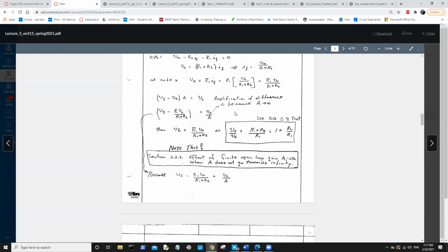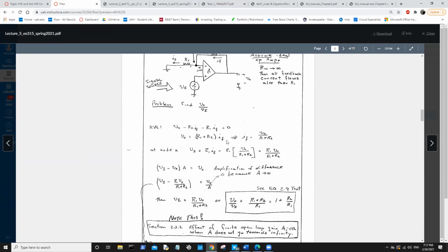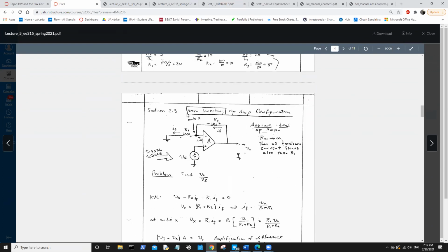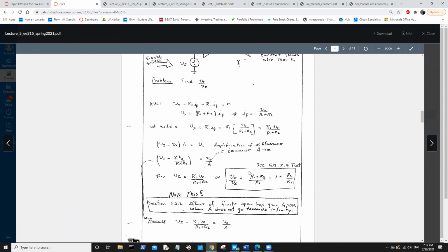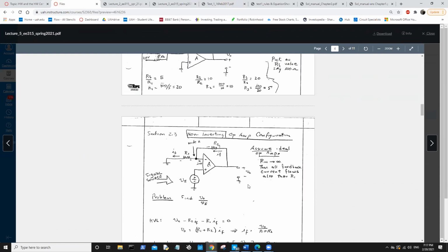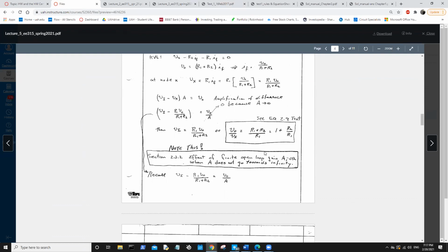And that one probably, if you want to look at the derivation, probably lines up exactly with the problem from the exam. Oh, that VO equals VI, that right there, that equation is fantastic. Is this for everything, or just this? Like, is this a general case for gain across the board, or just for this? For that, that's for non-inverting. So for inverting, it's the same thing, except it's negative.